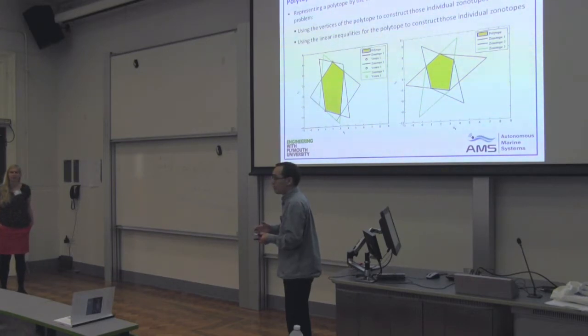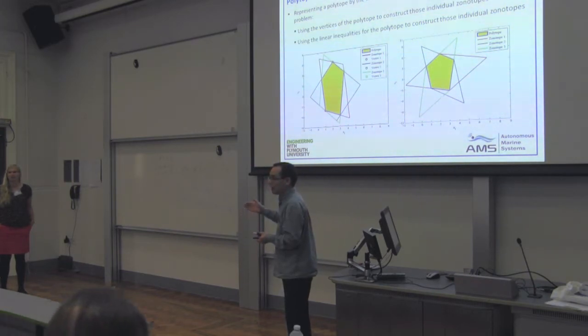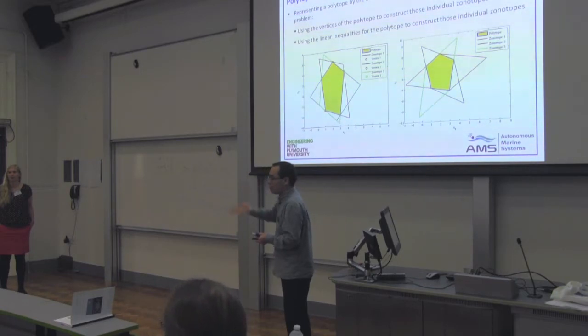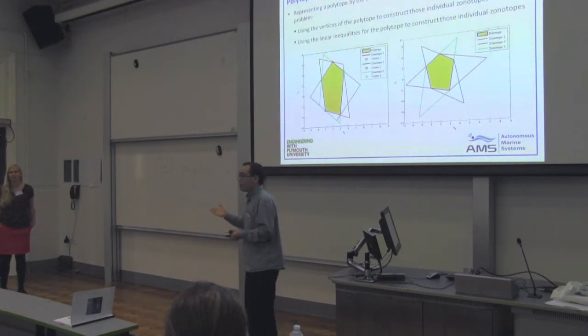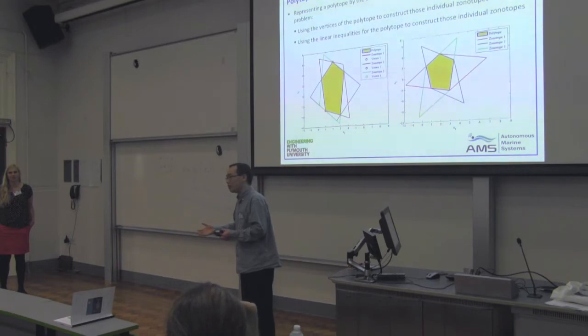Because for the estimation, you get one zonotope, but you propagate, and you get a more complex zonotope. And then you have observations. With observations, you will cut some constraints into your set. Okay. So essentially you will retain a polytope rather than a zonotope.